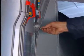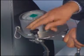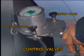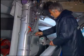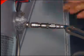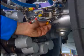On the top charging valve, remove the blanking cap. On the charging equipment, make sure that the control valves are closed and connect the filling hose. Do the same on the bottom charging valve.